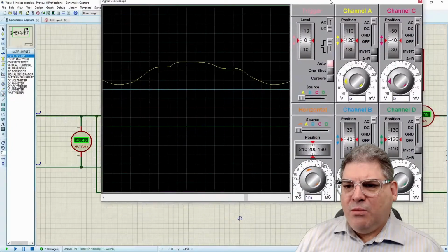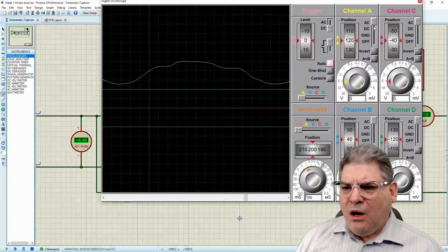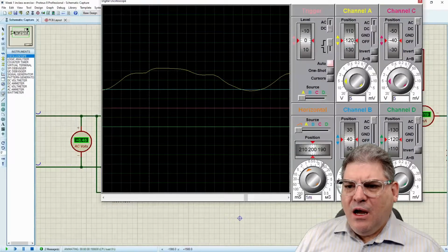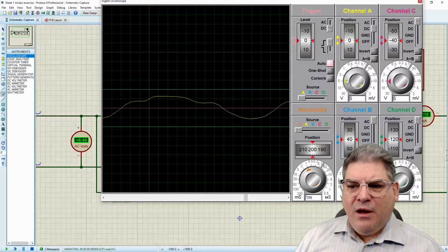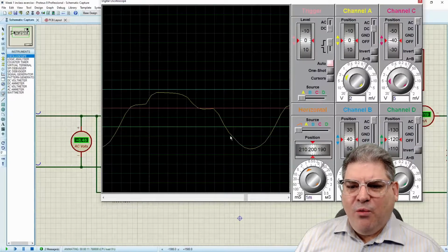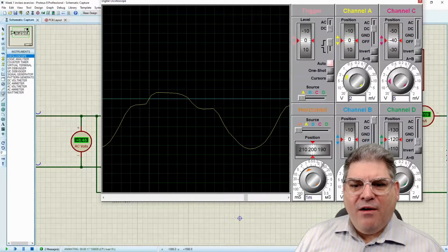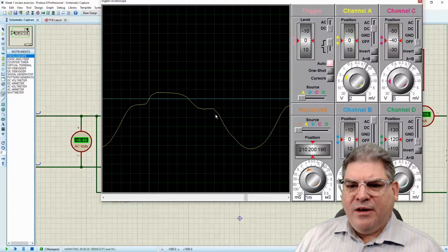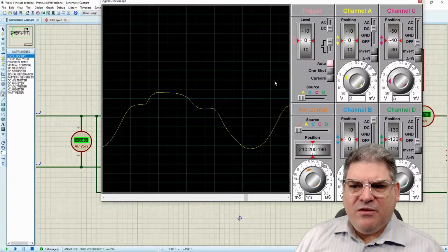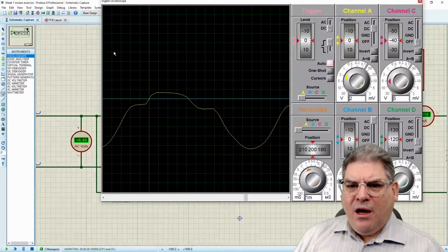And we're going to spend some more time talking about the oscilloscope later, but here we go. And so I'm going to flip you over to DC. I'm going to double click on the radio button. And as you can see, we definitely have a signal that's not what we expected. Okay. It's deformed and it's nowhere near a DC signal. And the other thing is that it all seems to be well below zero.